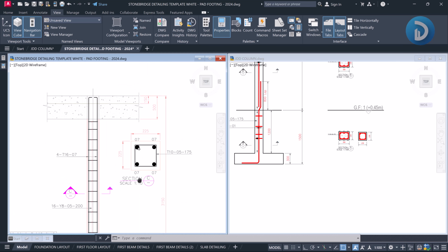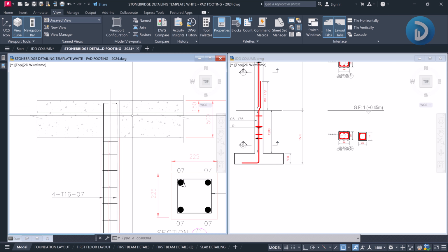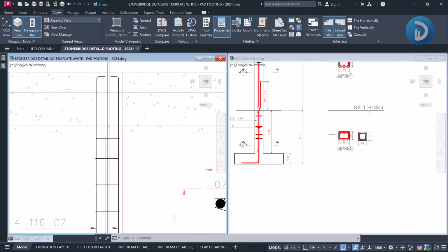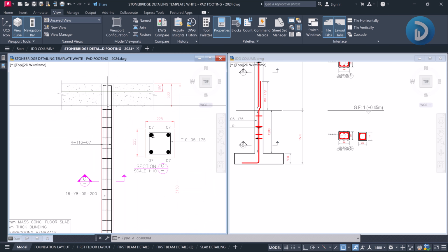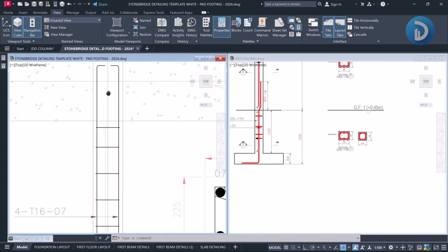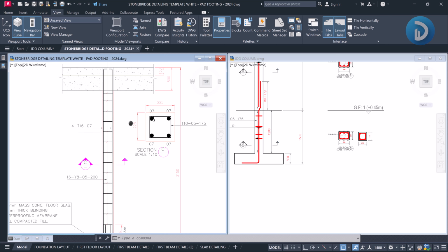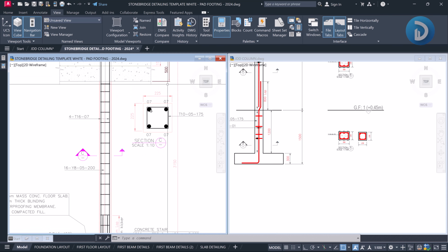And why you are doing so is this point where we have 500 millimeter or where we have our beams, this shear reinforcement will not be present there. Okay, so this links will not be required at this point. So it will only be required just below where we have the beams. So in order to get the adequate length, you have to subtract this 500 plus from this 3.15.